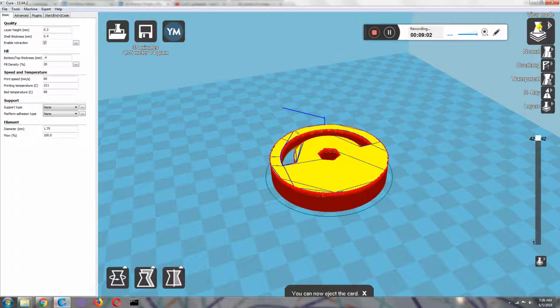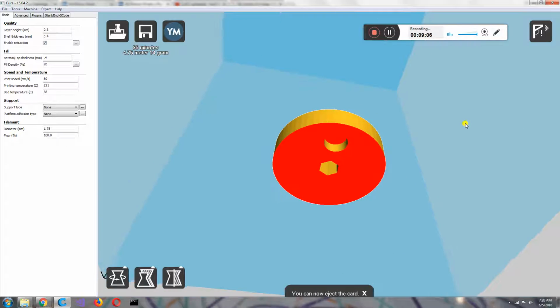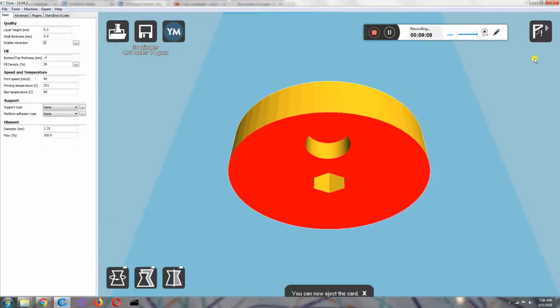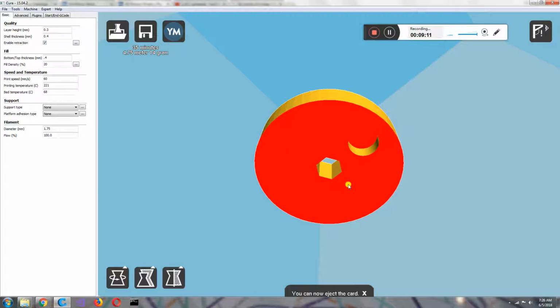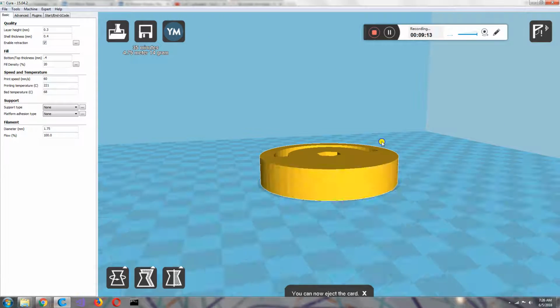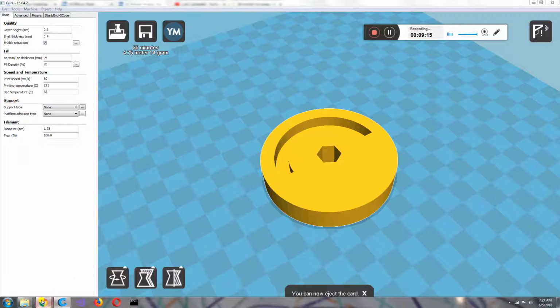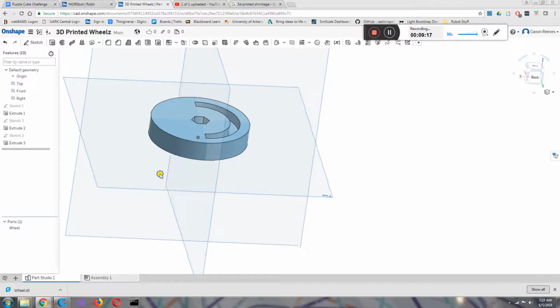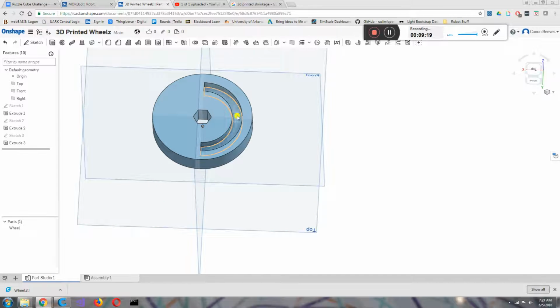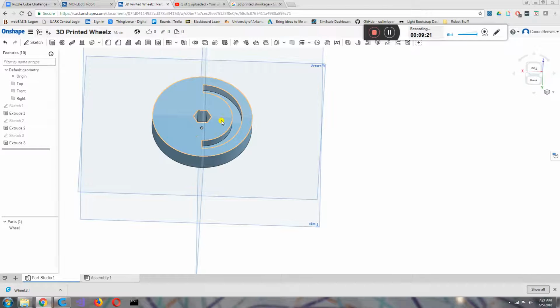There's actually a way to look for that. It's called overhang. So it'll show us where it's red. So right underneath there, it's very red. Not the main surface, but beneath that. So when you design this, just remember that it's okay to have it partially removed as long as it's only on one side.